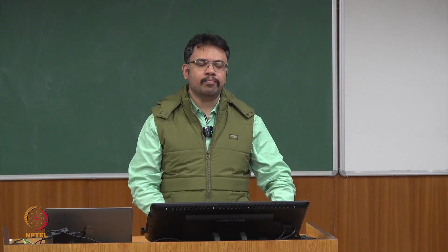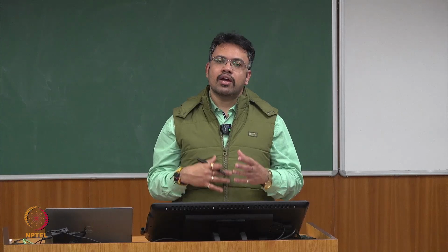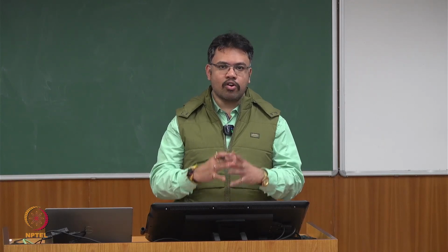Good evening, everyone. So previously you have seen primarily how the wave is propagating through the discrete metamaterial. We have seen undamped case, we have seen damped case, and we have also plotted the dispersion diagram. We have identified where the attenuation bands are happening, what is the effect of damping, and different types of cases like negative mass in mass metamaterial, negative stiffness, inertial amplifier, negative stiffness, negative mass inertial amplifier, all combining.